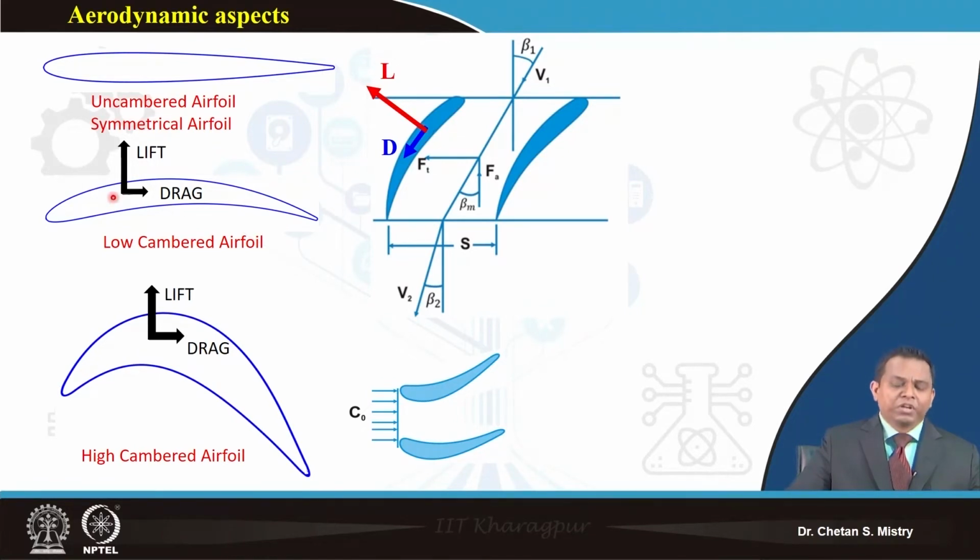Okay, so the majority of work or research is on what is happening on the suction surface of your compressor blade and what is happening on the suction surface of the turbine blade. Now here, these are the two airfoils I have arranged in such a way that this represents my flow passage. As we discussed earlier, here we have the inlet area and this is my outlet area. If my entry area is lower and my outlet area is larger, we can call this passage a diffusing passage. Okay.